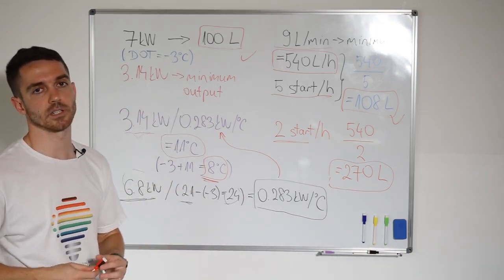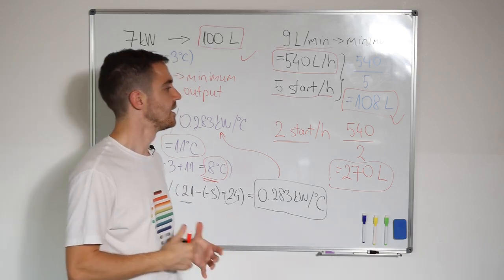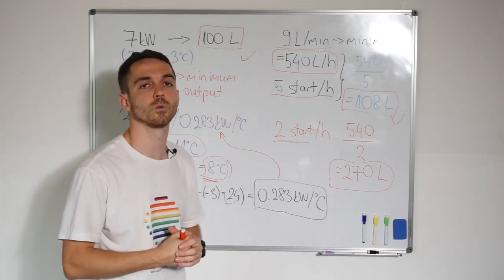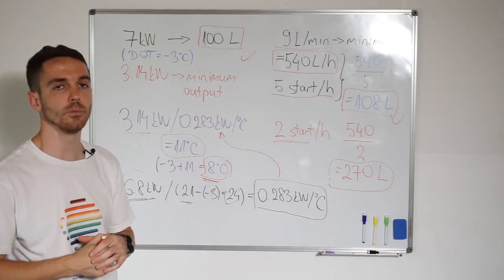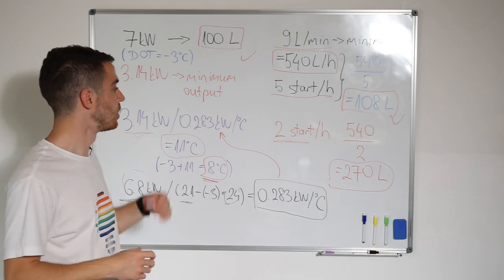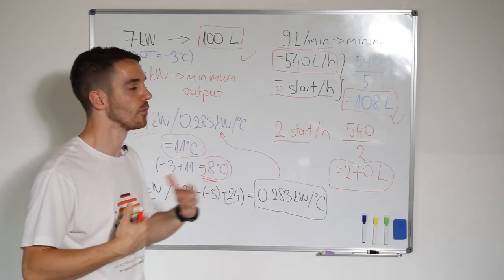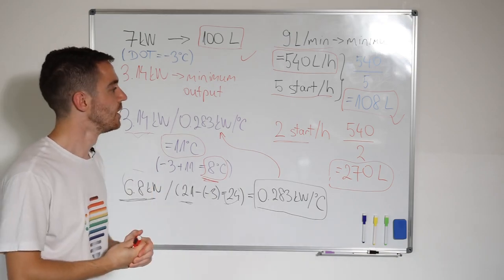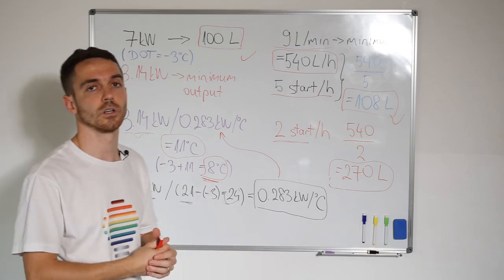Some new heat pumps, like Panasonic's new series, have defrost from the hot water side, which is a really good point if you don't have enough volume. But still, you want enough volume. Volume is like fuel for a car, so you need enough to have your system work smooth and work well.